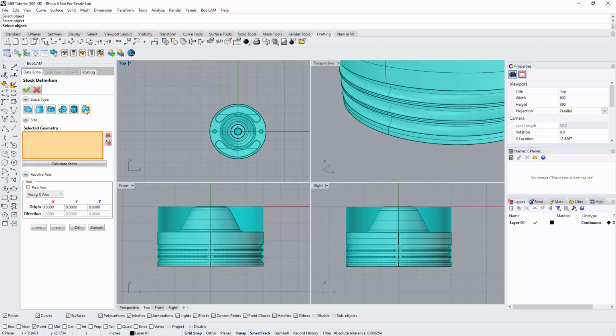This is something I primarily use with either lathe if I've already done some turning on a part, or maybe it showed up with some turning already done, or mill turn. Again, same situation. Maybe I have a piece of stock that's already been cut in some way. This allows me to pick a wireframe for a part and then revolve it into the stock that we want.